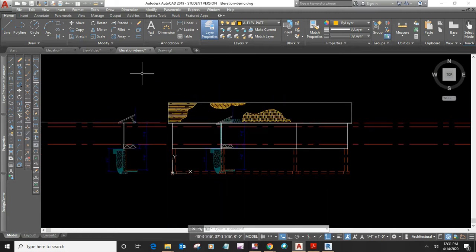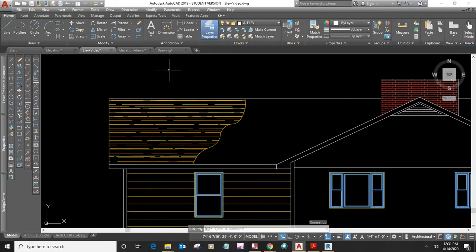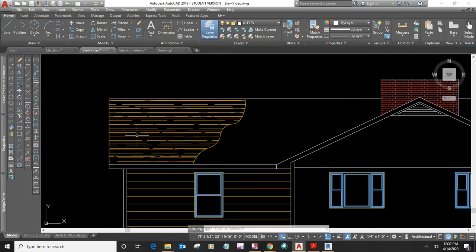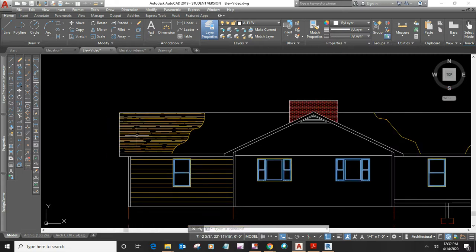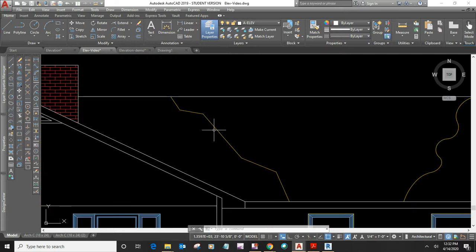What we'll do is some polylines so we're not hatching the entire area, because that just overloads things. What I did here is I drew a polyline and put some zigzags in it, and then trimmed it at the ends.